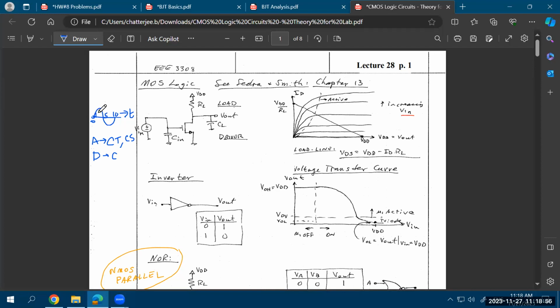So that's what is meant by sampling, that you sample the value of the signal at certain discretized points. Even though your original signal was continuous time and continuous signal, if you take samples out of it, your time will not be continuous anymore. So time will be discrete. If you take samples, you'll be discrete time, but still you'll be having a continuous signal.